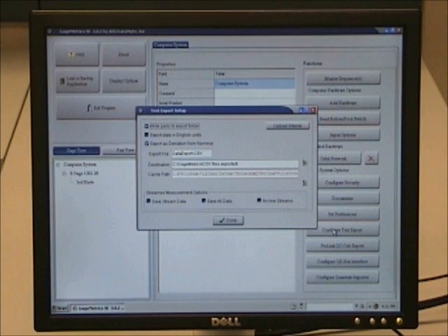Configure text export is one that you're going to definitely want to pay attention to because it is where your data is being saved. When you save that data or you read, it captures your data and it saves it to a log file somewhere. You can set this up to save to a CSV file, or you can set it up so it goes out to a simple comma delimited format. CSV is probably your easiest and least amount of operator intervention.